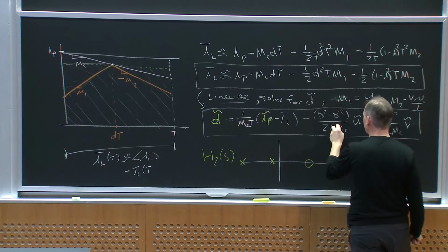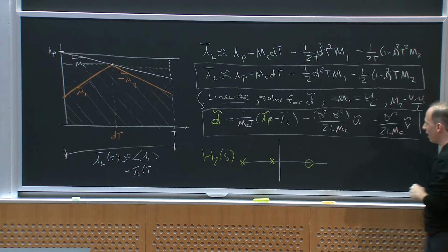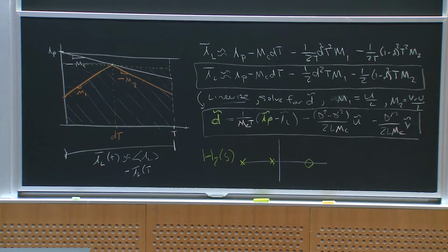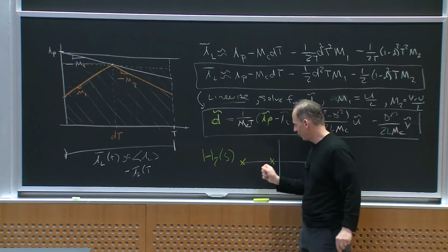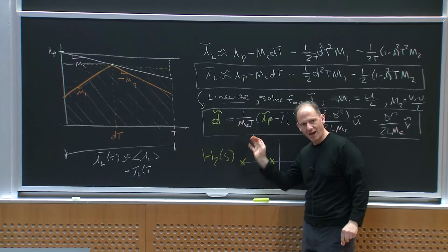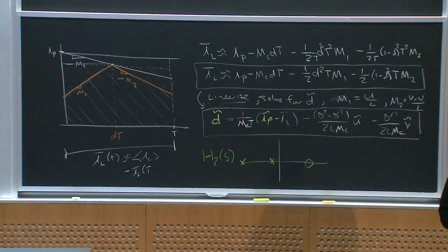My local average linearized dynamics of my converter are not independent of MC, okay? And when I told you that I get a really low frequency pole and then a high frequency pole, both on the real axis, that's sort of when MC is small.